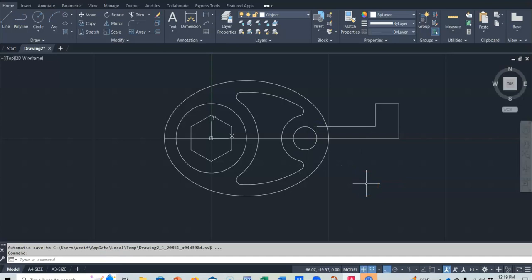All right. There are a couple little things you've got to do to clean this up. We could do it before or after we mirror it. If we do it now, it's a little more efficient. So again, I'm going to go back to the fillet command. In this case it's still a radius of 2. So I'm going to select this one and this one. That creates that nice radius. And then I'm going to use the chamfer command. Chamfer is where it's squared off.